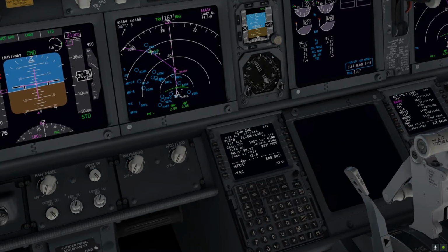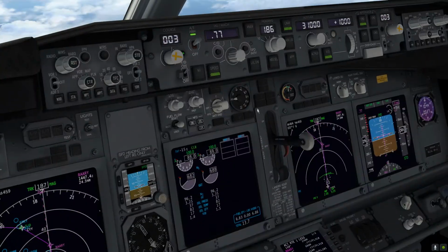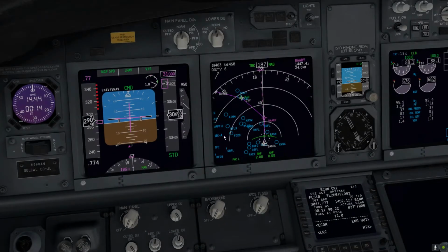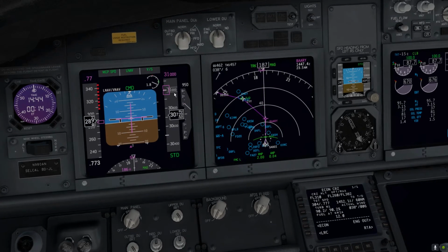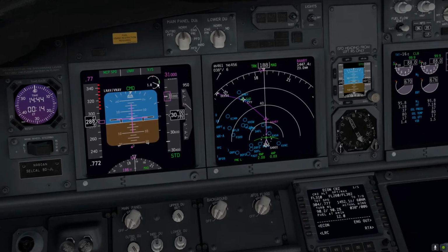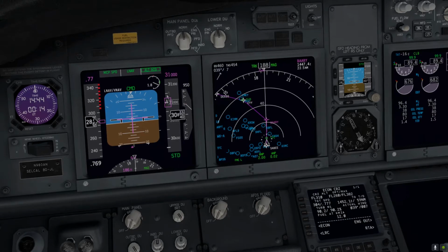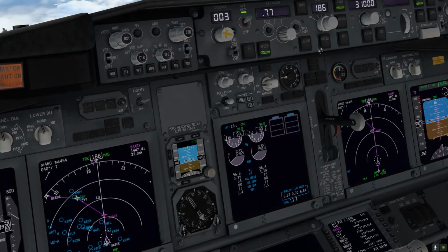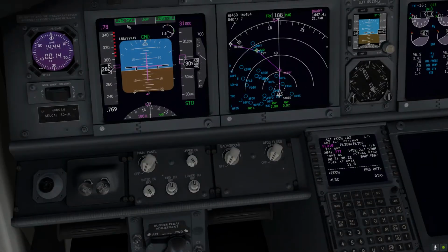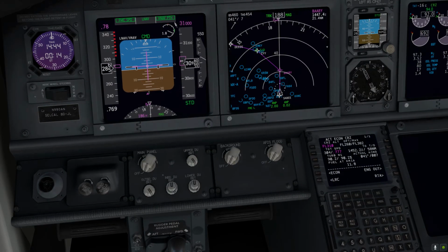And let's see here, we have a 0.77 cruise. Yeah, it looks nice like that. So waiting. Now we are waiting as well for the FMA to change in FMC speed and VNAV path. And waiting for that. Alt acquire. Now going back into VNAV, and now we have FMC speed and VNAV path.